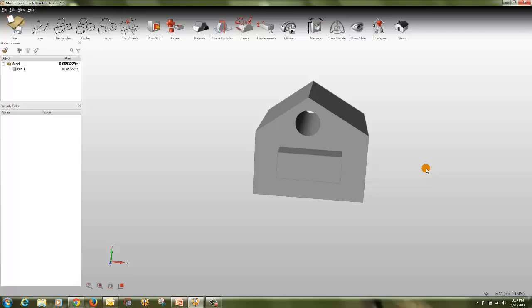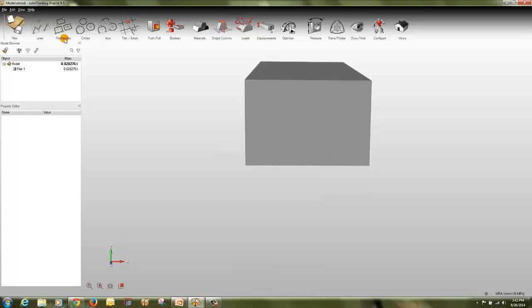Sketching curves on an existing face breaks the face into subfaces. These can be extruded into solid material by pulling outward with the push-pull tool, or turned into a hole by pushing inward. Open curves that cut across the edge of a face can also be pushed or pulled, either to create new geometries or to carve away existing material. So we will see some of the options like lines, rectangles, circles and arcs. Now we will see some of these sketching options.